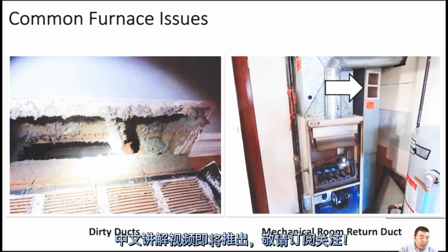So beware about the mobile home. Mobile homes typically don't have the return air duct. That means the furnace just gets the return air from the top of the furnace. There's no duct, and the filter is normally just on the top of the furnace. You cannot see the return air duct, but sometimes you can still see the supply. A return air duct can't be installed in the same room as an appliance, like the right picture shows us.